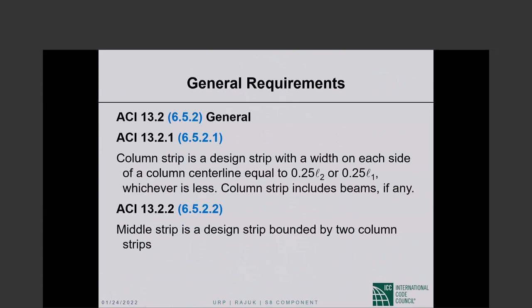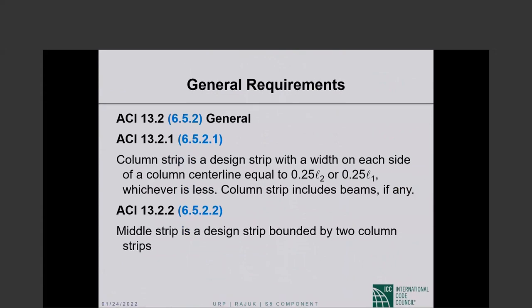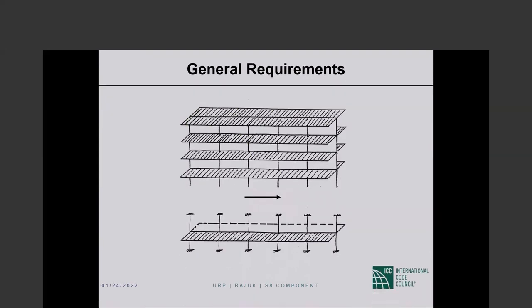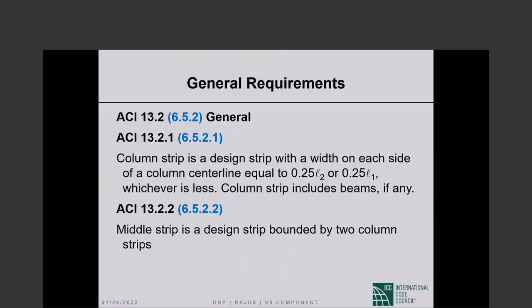So we now talked about design strip from panel center line to panel center line. Okay, keep that language, that terminology in mind. Design strip, I will use it quite a bit. The design strip, as I was trying to indicate earlier, is divided between column strip and middle strip. Column strip is a design strip with a width. I think a picture will be better.